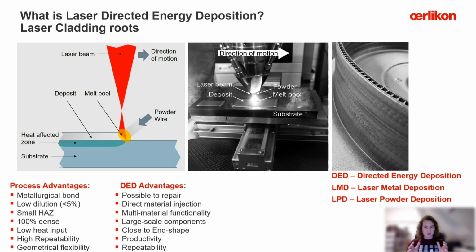If we work with powder nowadays with nozzles, you can get up to 90% material consumption, ending up in very high deposition efficiency. If we talk about wire DED, we consume 99% of the material, and this is an extremely high number. So it's a very efficient and sustainable process in terms of raw material usage. I will give a detailed discussion about the differences between powder and wire in my next lecture.